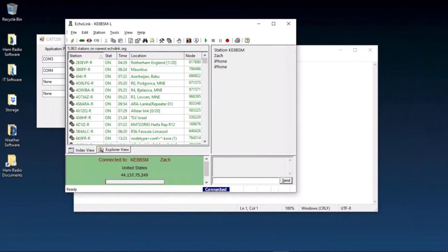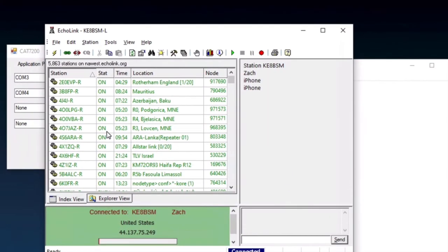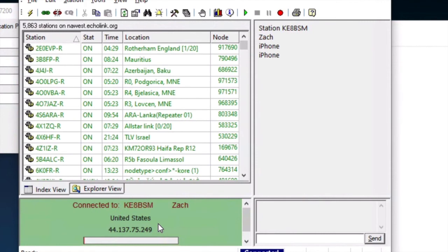And to go back to what I was talking about earlier, when I talked about menu item 55 on the radio, the USB squelch level. Let me make sure I have that right. Yes, USB audio squelch, and turning that on. If I turn that off, I'll show you what happens. This is with it off. See? It's off. And this is all that you would hear.